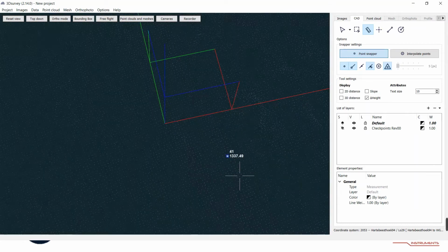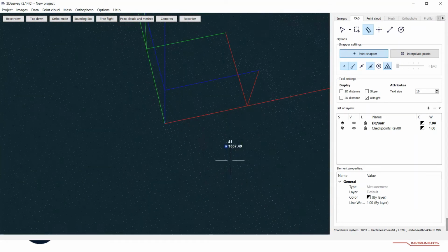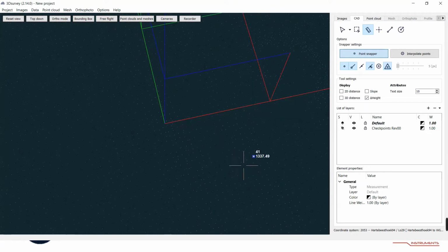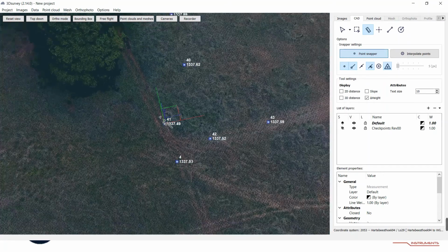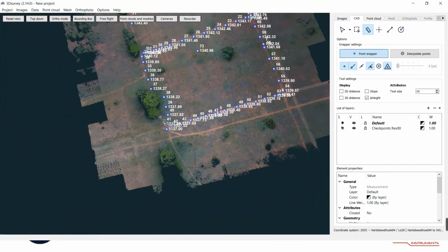Also, this is a vertical check that we're actually doing here. So it's not a horizontal check, this is just a vertical check. We know that based on our data that our vertical checks should actually be spot on when we look at our GCPs. So what we just want to do is a bit bigger error, 80 mils, 70 mils, 70 mils. Okay, right, so not that bad.